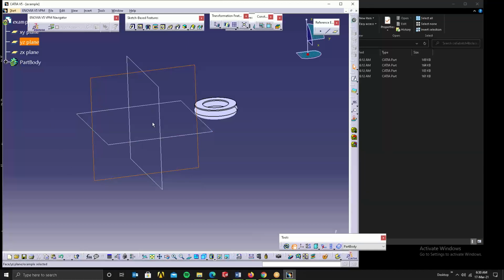See, in the previous case, I selected the vertical line. I didn't use a plane at all. I used a vertical line, and I can use vertical or horizontal as the center axis. I didn't use anything else. So this is much simpler, right? You just have to select the reference element, and you can do this with ease.